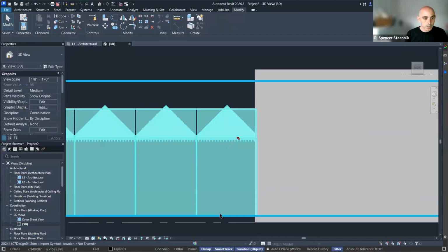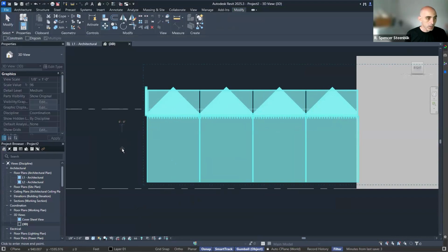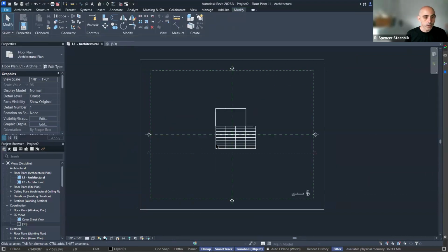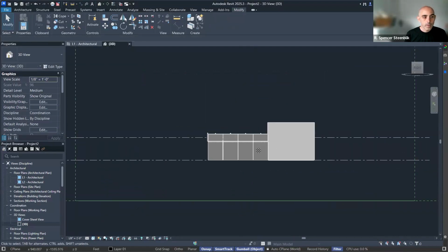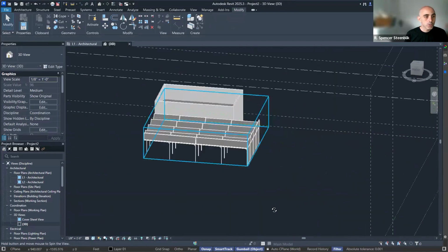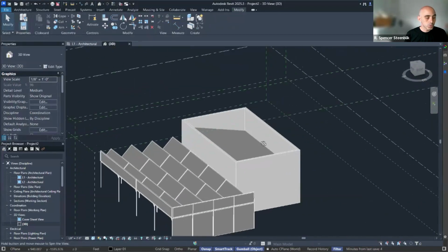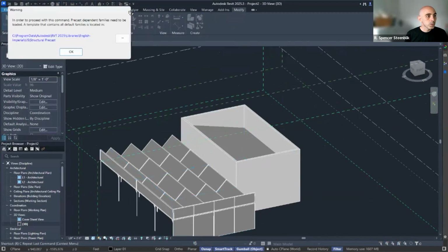It's still up a little bit, so I'll come down even further. MD, and I like this because it will lock it in place. Okay, there we go. Now we're golden. We've got it right in place. Oh, and it's showing in that first floor plan now. So there we have it. Now I think the next thing to do will be to put a roof on, RF. Oops.